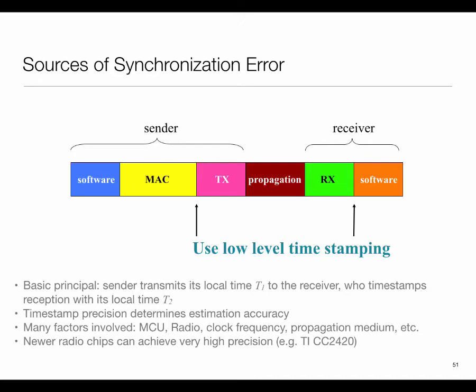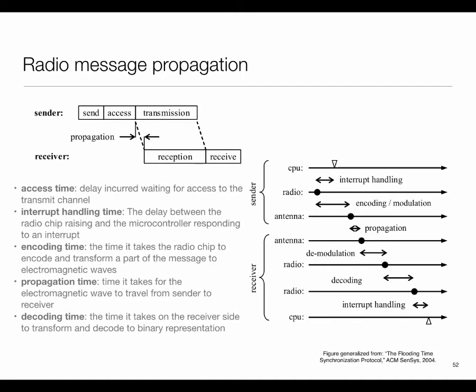I take one node and send packets to multiple other nodes, all of the same brand. You will see some variation there. Some of that variation comes simply from the native frequencies. The clock crystals at those nodes are slightly different, even though they claim to be the same. So manufacturing variations come into play as well. Using these insights, there have been a lot of interesting pieces of work.